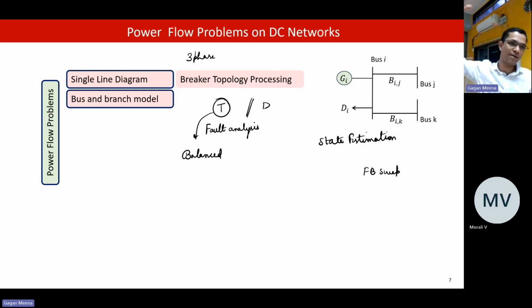the more we go up higher in voltage level, the three phase... at distribution side, we have small loads. So they create minute differences because voltage levels are also very small, 240 volts to 230 volts. That will create small difference in the voltage if unbalance is there. But when we aggregate those loads, and as we move up, because we have transformers and tap changers, they try to keep the voltage at around 1 per unit. So system balance is the difference between transmission and distribution.